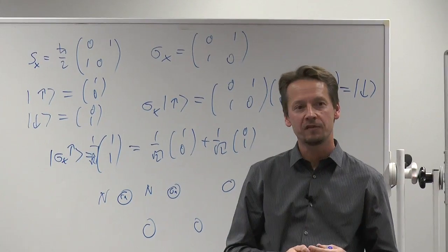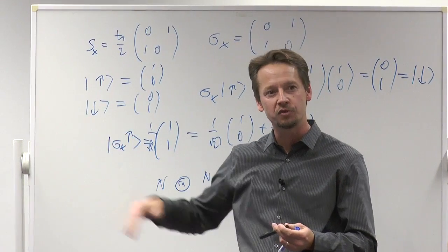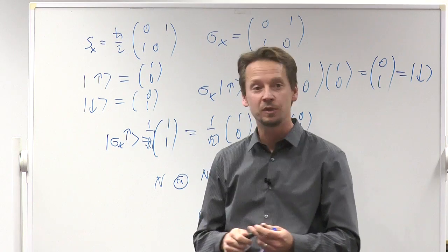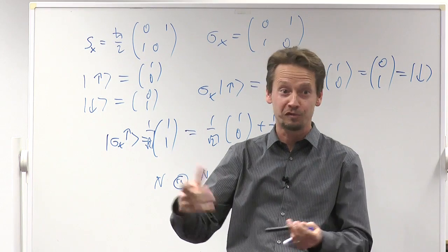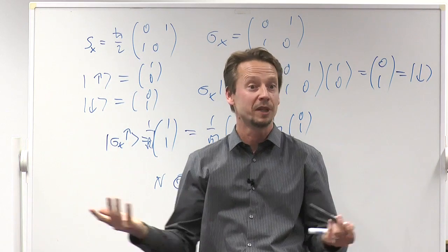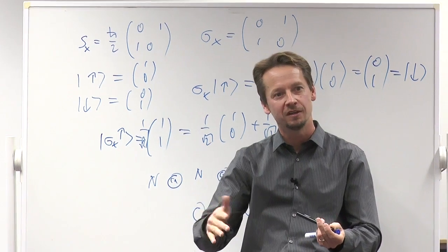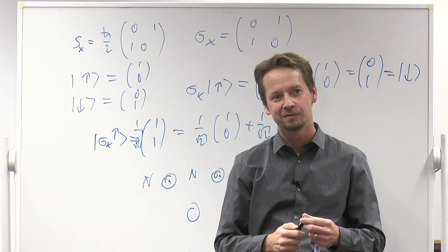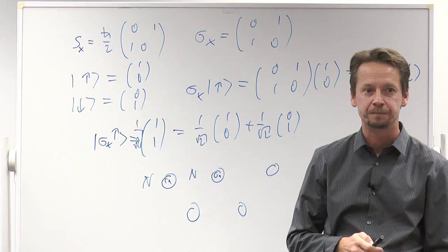And then the nitrogen, we have to crack the nitrogen bond. If you just let gas into a vacuum chamber, you will not make copper nitride because the nitrogen bond is very strong chemically. So you need to break that. We do it very simply by using that same sputter gun that accelerates the nitrogen to something like a kilovolt. That's definitely enough energy. That kilovolt of nitrogen then hits the surface and gets implanted somewhere in that material. If we then heat that up to proper temperatures, like 300 degrees C, this nitrogen comes out and self-limits to only a single layer of this copper nitride. So we're using recipes developed by other people mostly to do this.